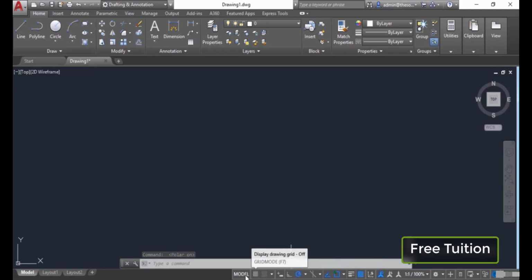So right now all of these options should be off except this polar tracking. Only this should be on. Also make sure that object snap is on, and object snap tracking is on. So we are keeping only three options: polar, object snap tracking, and object snap. These three options should be on. The rest of the options can be kept off.